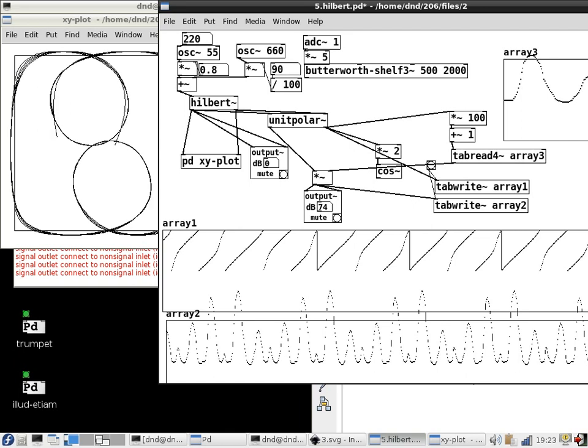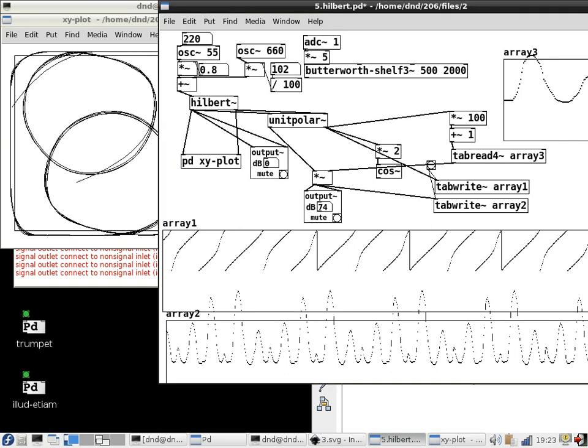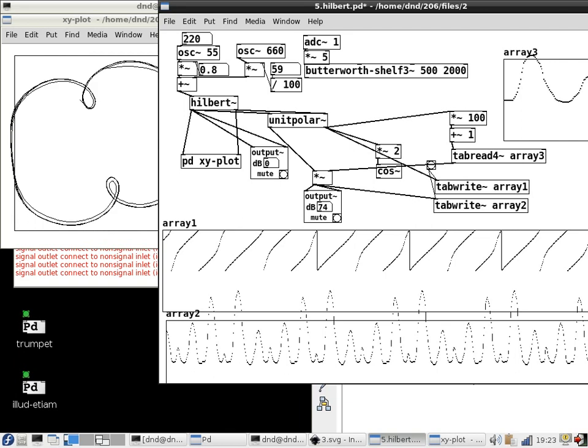The good news is that that's actually not a discontinuous change, because right as the thing passes through 0, it's got 0 amplitude, so you don't hear a discontinuity. It's just that the nice theory that we put around the thing, which is roughly true when the thing is dominated by the fundamental, is no longer true when you start doing stuff like that to it.